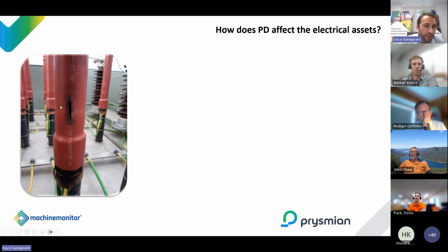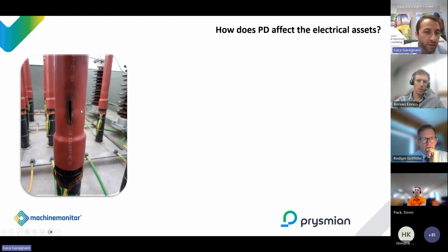So this is actually the same location where I showed a picture before of a rotating machine stator bar, where you can see the discharge, right? In this case, we probably had the same problem. The stress gradient system, which should decrease the surface stress in the transition between zero potential on the semicon and full potential on the XLPE, has not been done properly.